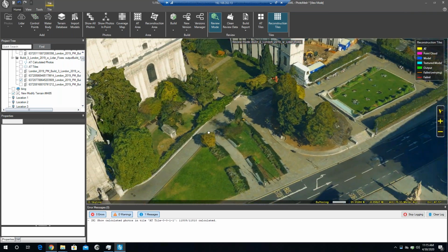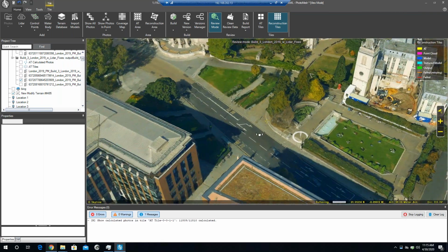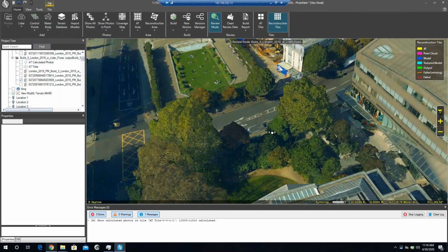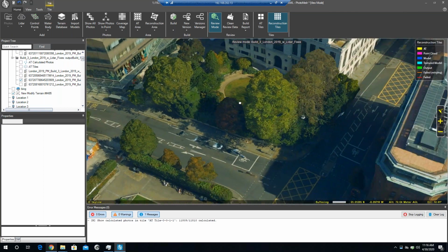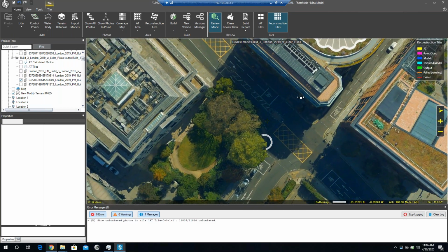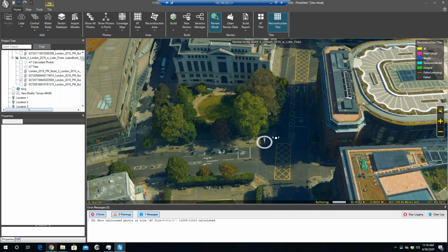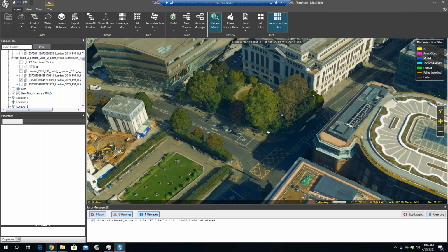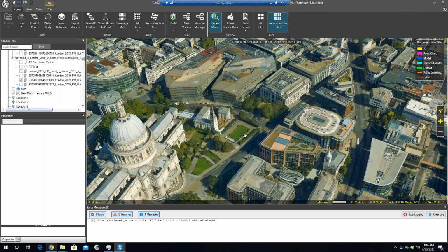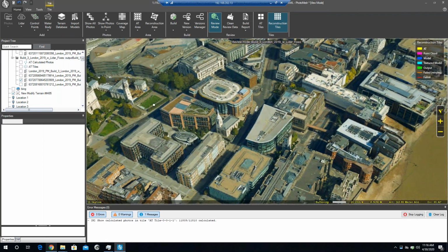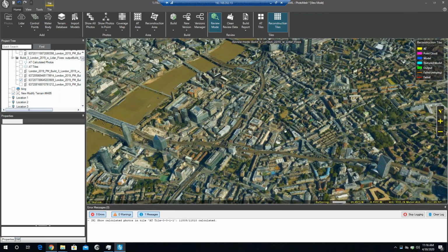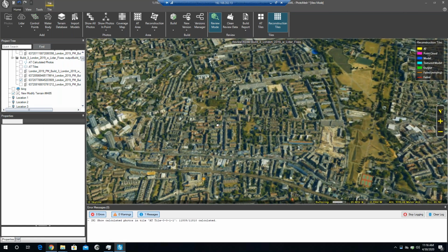And with the combination of the LiDAR, we can also see the quality of the trees is much better, the density of the vegetation from the LiDAR correlation, as well as sidewalk data or information, which is from the top view obstructed by the trees. With the LiDAR penetration, you're able to get a lot of information underneath that and really get a complete view, especially in urban areas and dense areas where there's a lot of buildings that are close together and tight vegetation.